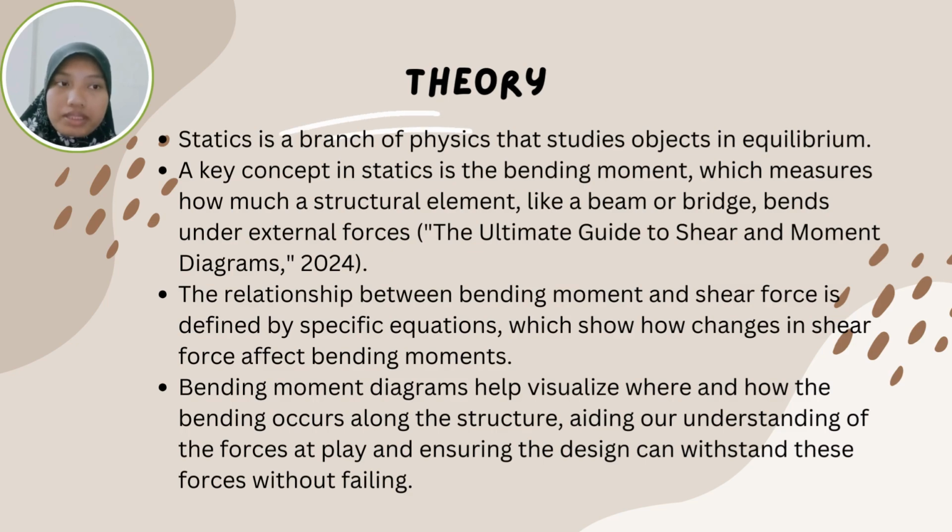Statics is a branch of physics that studies objects in equilibrium, so a key concept in statics is the bending moment, which measures how much a structural element, like a beam or a bridge, bends under external force, as depicted in Ultimate Guide to Shear and Moment Diagrams 2024. The relationship between bending moment and shear force is defined by specific equations, which show how changes in shear force affect bending moments. Bending moment diagrams help visualize where and how the bending occurs along the structure, aiding our understanding of the forces at play and ensuring the design can withstand these forces without failing.